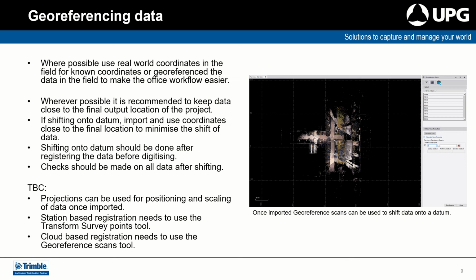Scale factors are a consideration for scan data. So for long linear scanning projects, shorter sections may be needed to account for scale factors if it is going to be a consideration over a long distance. Also, when shifting data, it needs to be considered that scale factor may become an implication. So it's always worth noting what package you're using and how that package handles scale factors and what you need in your processing before fully undertaking a scanning project.